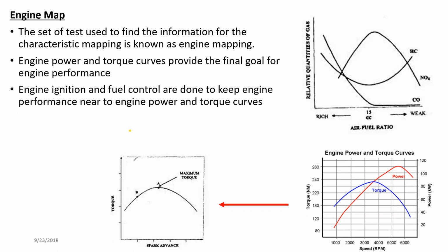So for each and every position, once you develop the graphs, you have a set of graphs. Once you combine all of these graphs into a sort of booklet, you end up having the engine map, as I explained previously. By combining different RPM ignition maps, you can get the total or complete map, right?